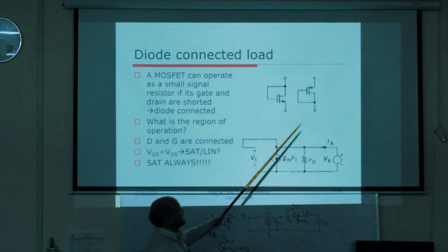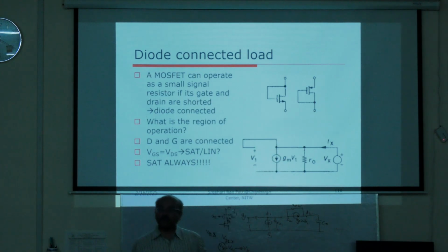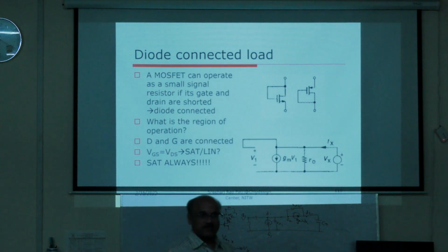So we can see that as VDS is varying here, VGS is also varying, because drain and gate are connected together. As VDS varies, VGS also varies. As VGS varies, current is bound to vary. Though it is in saturation, because VGS is also varying, obviously, see earlier what we said is as VDS is varying, keeping VGS constant, current is constant. Yes. But here I am violating that rule.